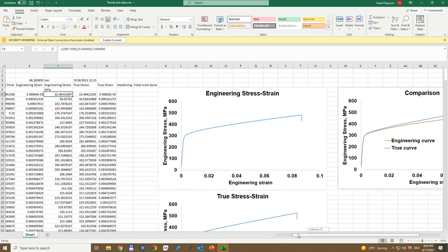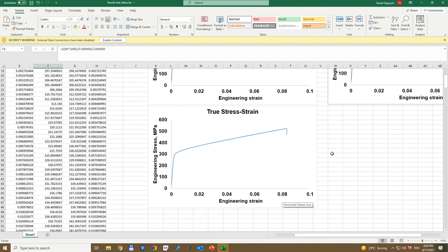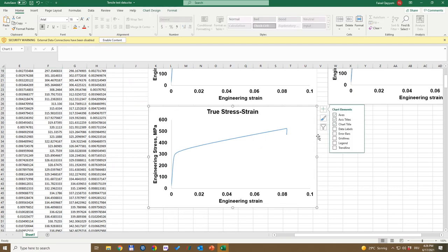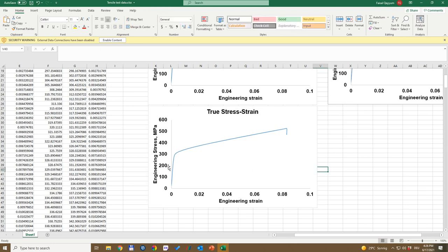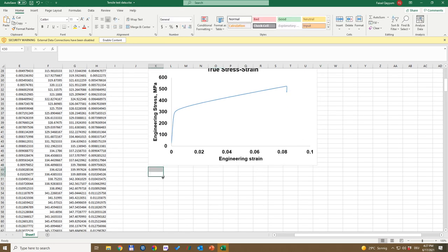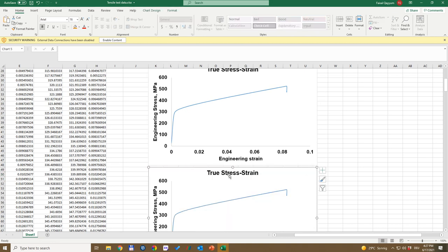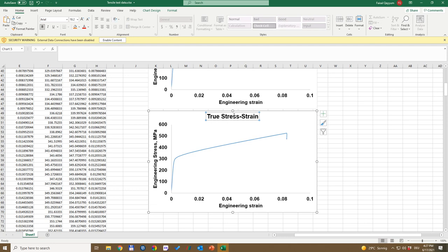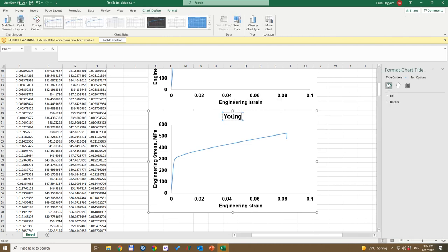So if I come back here, there are quite many easy ways of doing it. So one way is to divide stress with strain. The other possibility is to see the slope of this line, and that is what I will do here. So that is a graphical way of doing it. We can quickly do it here. So what I will do is Young's modulus.